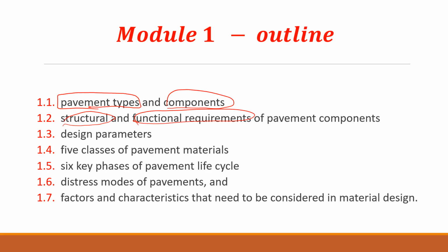The structural part is that your pavement layers should be designed in a way that they are able to withstand the loads coming onto them without any deformation, without cracking. That part is the structural requirements. Volume stability, the propensity to crack, or the strength, they all come under the structural requirements.